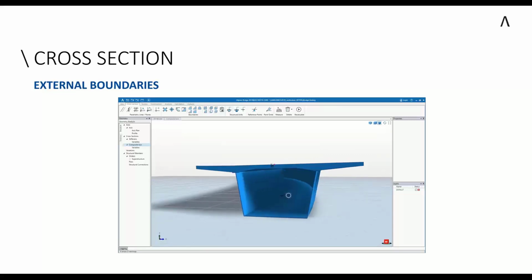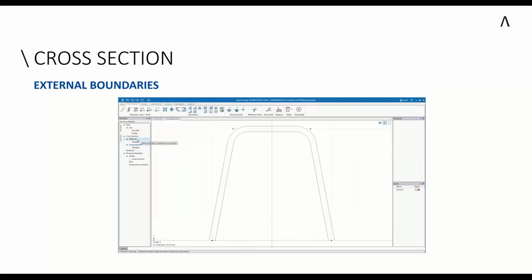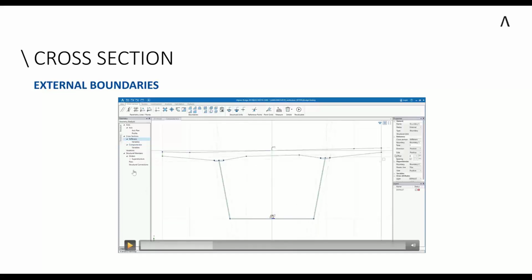And here in this animation, you can first see how this is handled. So I have here just a steel section. Then I click this external boundary function. I select the boundary I want to insert. Maybe let me just quickly stop this. You can see, so they're on the same level. Right here, there's my composite box, and here's my stiffener. So they're on the same level. But now by clicking this external boundary function, I will just select another cross section to be added to another cross section. And now here, I will just type in the numbers.